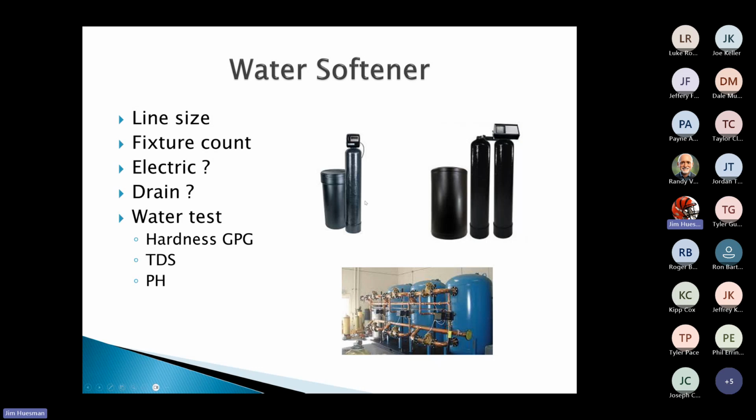Before I jump too quick, you saw me push over here to a single tank and a dual tank. When you see single or double, it doesn't mean the double must have extremely hard water. That's not it. When this thing is in operation, this is where we ask, what type of facility are we working with? Say we're working with a pet store. The hours of operation are roughly between 8 and 8 o'clock at night. But when this thing goes into regeneration at 2 o'clock in the morning, pretty much your water will be shut down.